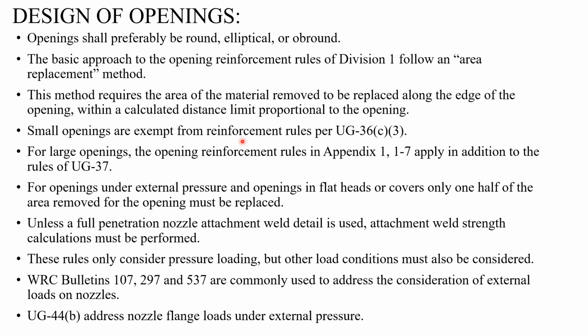Small openings are exempt from reinforcement, UG-36(c)(3). What is UG-36(c)(3) and what the exemptions are, we will see on the next slide. Large openings we will see in the next video. We will not cover them over here because there should be some limit to the video. I cannot put all the detail in one video, right? So we'll see it in the next video.